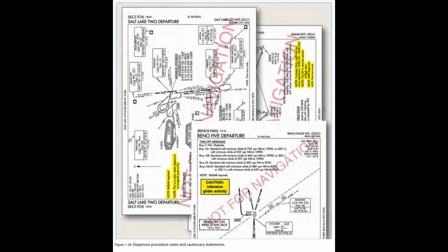3. Radar DP. Radar may be used for navigation guidance for SID design. Radar SIDs are established when ATC has a need to vector aircraft on departure to a particular ATS route, navaid, or fix. A fix may be a ground-based navaid, a waypoint, or defined by reference to one or more radio navaids. Not all fixes are waypoints, since a fix could be a VOR or VOR/DME, but all waypoints are fixes. Radar vectors may also be used to join conventional or RNAV navigation SIDs. SIDs requiring radar vectors must be annotated radar required.